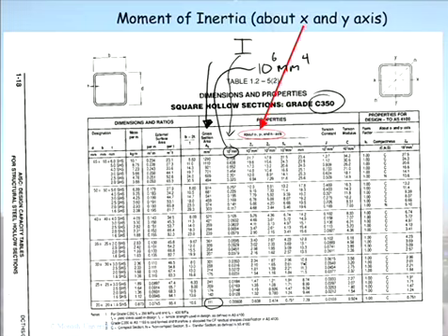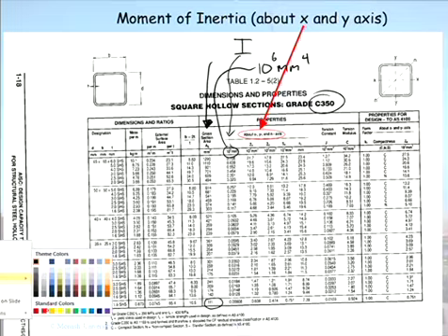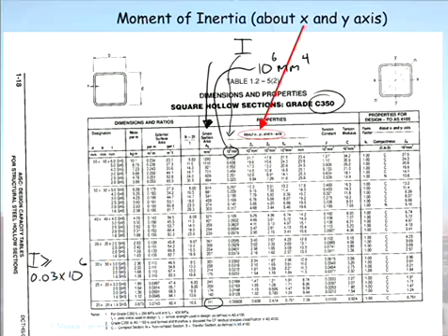So coming down that column there, the smallest I value is 0.006, and we're looking for a value just greater than 0.03. So can you see it there, 0.0316? So we want an I value which is greater than or equal to 0.03 by 10 to the 6. So coming up our table here, this column here, I, it is that value there, which makes it this section here.